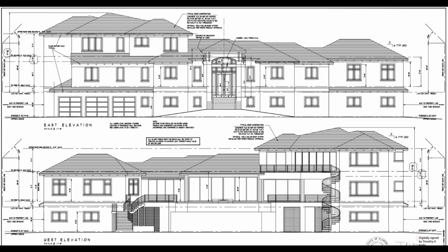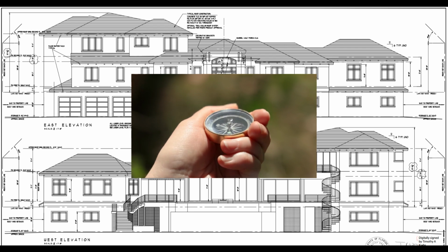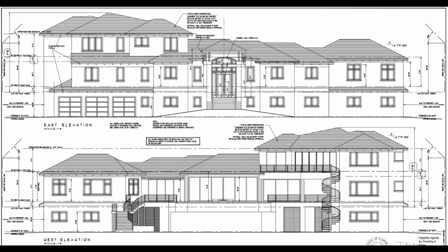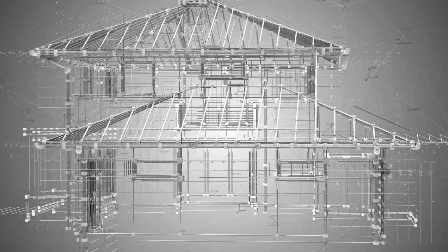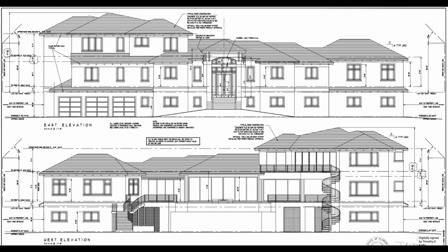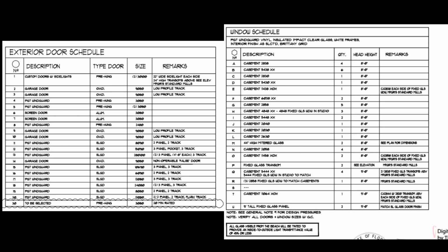Another type of architectural page are elevation views. They are views of the exterior of a building or structure, usually designated by north, south, east, and west, but usually represents front, rear, left, and right. The information found here are window and exterior door location, building height, roof shape, overall building size, and sometimes they discuss exterior finishes and cladding. Cladding are parts of a building that are fastened to the exterior, such as roof material, soffit and fascia material, etc.